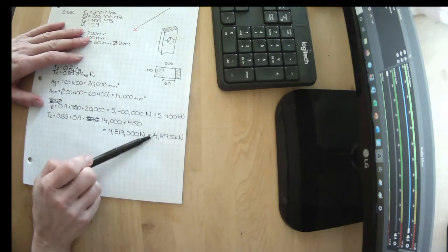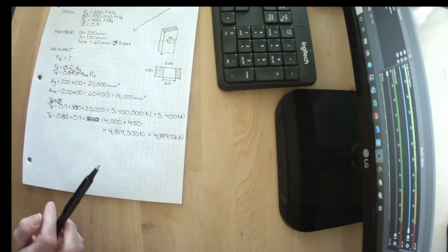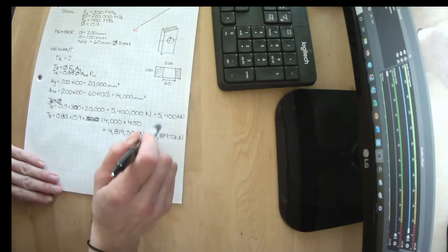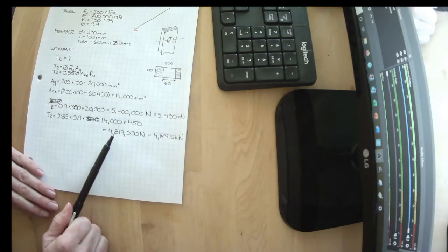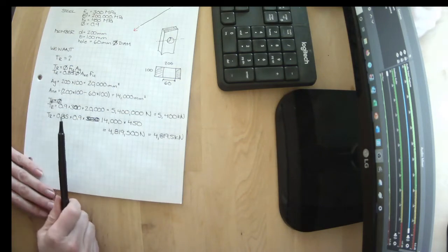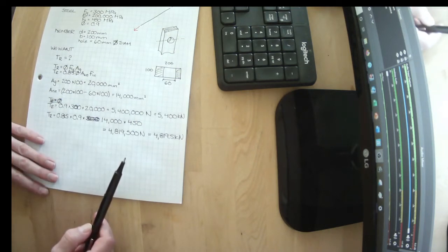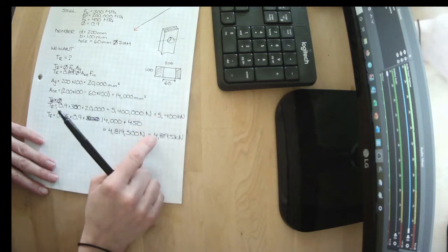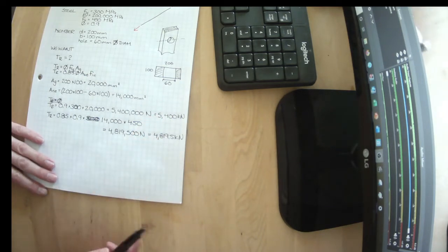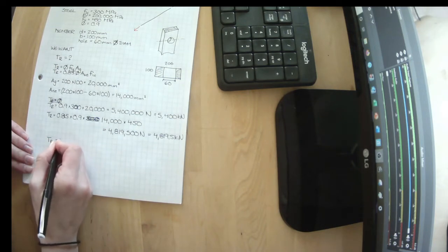They're both calculated. The lower one is the maximum our brace can see. If we said that these are both the maximum force our brace can see, and we have 4,000 kilonewtons on it, it works no problem. If we have 5,000 kilonewtons on it, it works for this equation, but not this equation, and it would fail. So Tr for this brace is